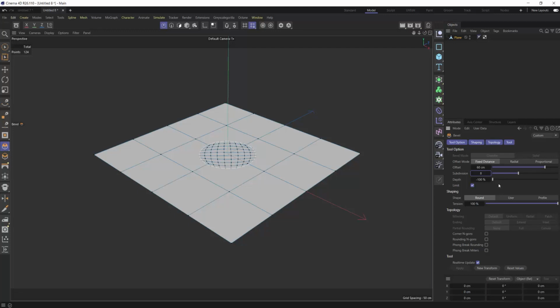When we're working with hard surface models, we want to try to keep our geometry as low polygon as possible. And so this gets really heavy. And we're going to talk just in a moment about proper topology being quads or tris. And that's our goal here. And in order to make the polygons around this proper, there's going to be a lot more work to do here. And you'll see in just a second. So let's bring this back down to 1.